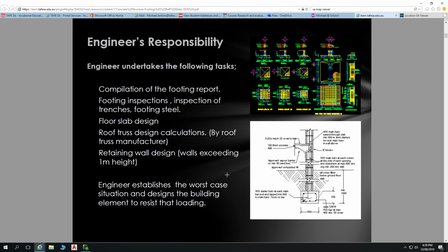So none of us are going to be designing raft slab footings. I'm not going to be designing raft slab footings. I'm going to have a general idea about what's going to be specified, and I'll make plans accordingly. I'll be thinking, okay, in this particular site we're going to have beam spacings at around that 2 meters. It's probably going to be 600 deep, 300 wide, etc. Think about that's probably what the engineer is going to specify. But what I'm not going to do is specify that footing system.